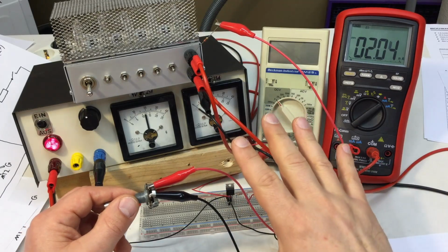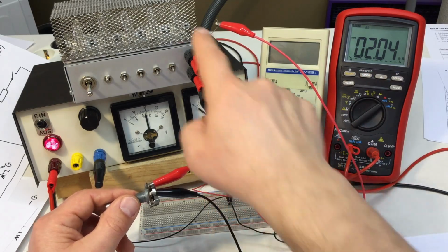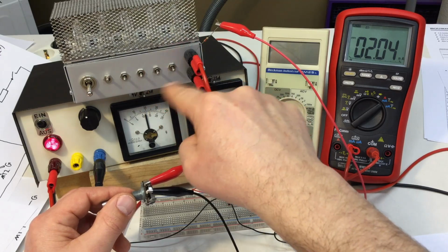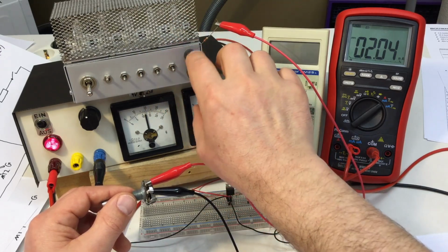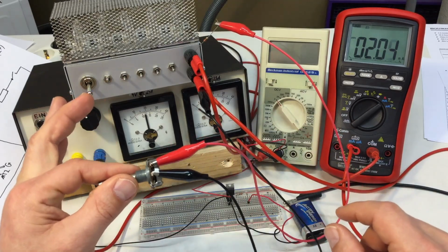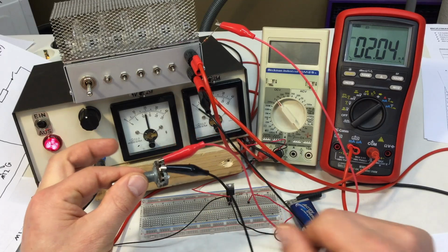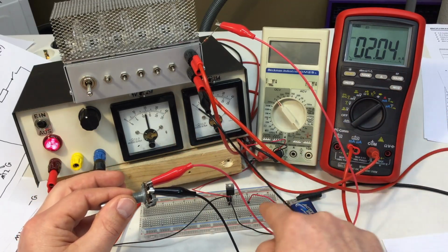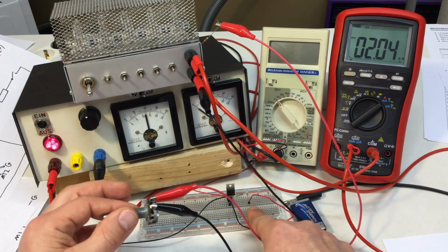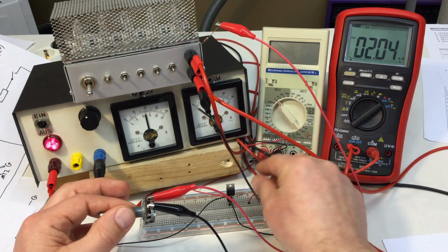So let's measure quadrant 1 and quadrant 2. I wired everything up for quadrant 1. I'm not using my electronic load here, it's just used as binding posts. The current into main terminal 2 is controlled by that resistor and that potty, and it's currently at 2 milliamps. My gate is constantly supplied with some current.